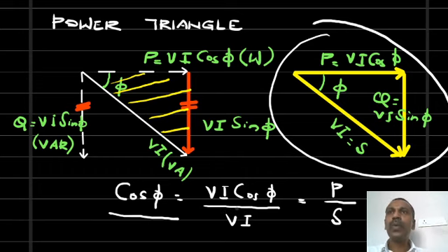If you consider a motor, if it is an induction motor, it needs both active power and reactive power for its operation. When you give electrical power, it is converted into mechanical power. Actually, the active power is converted into mechanical power. But why do we need the reactive power? It is to set up the magnetic field. So the reactive power sets up a platform in which the energy conversion takes place.